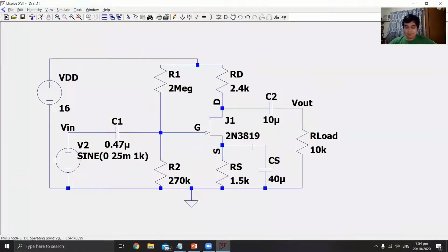The advantages of JFET are that these devices have the advantage over BJT of having an extremely high input impedance along with low noise output, making them ideal for use in amplifier circuits that have very small input signals. Also, FETs are less affected by radiation compared to BJT.